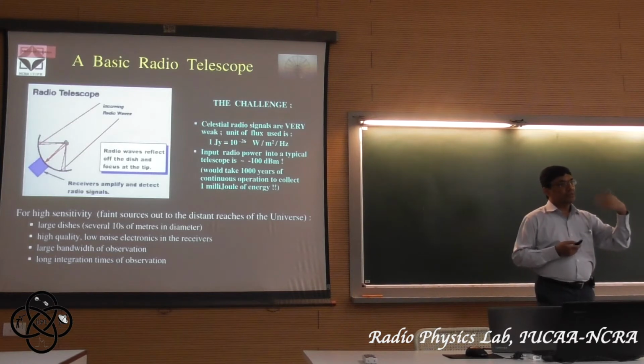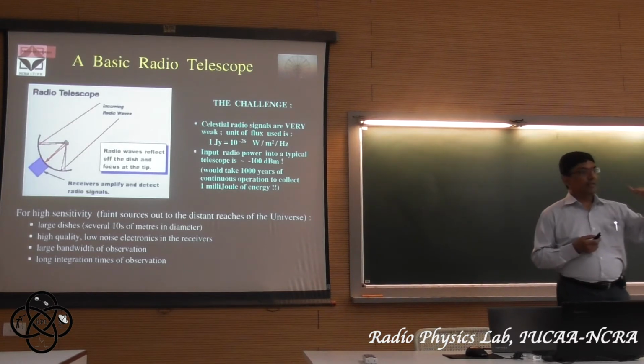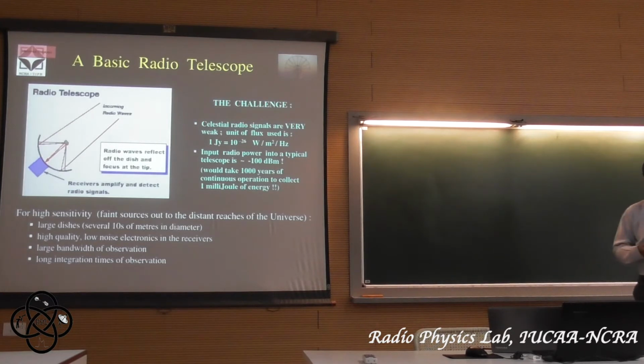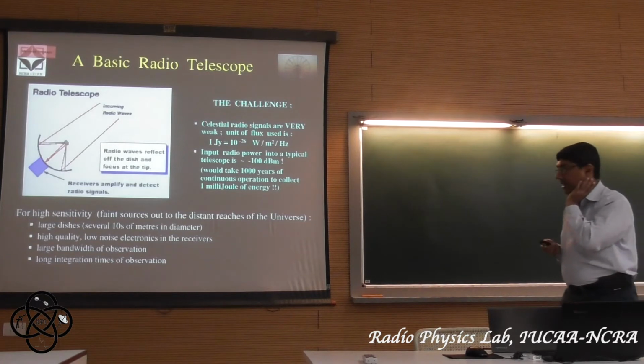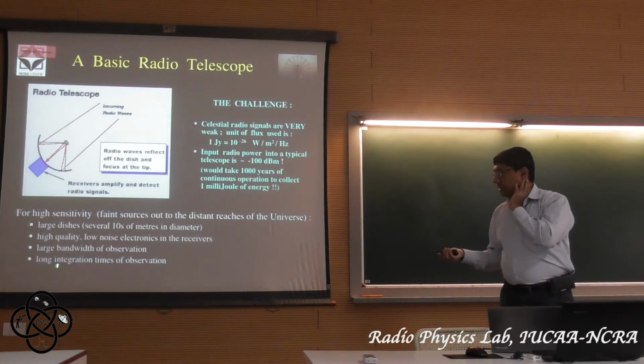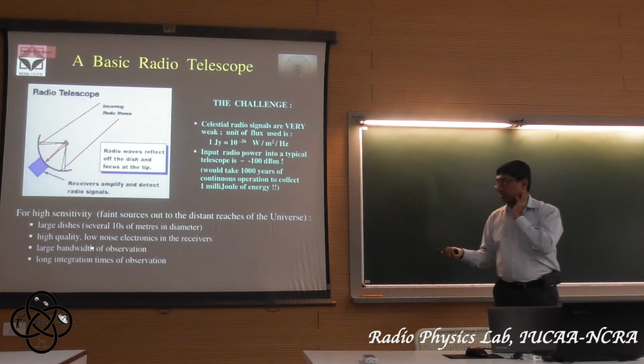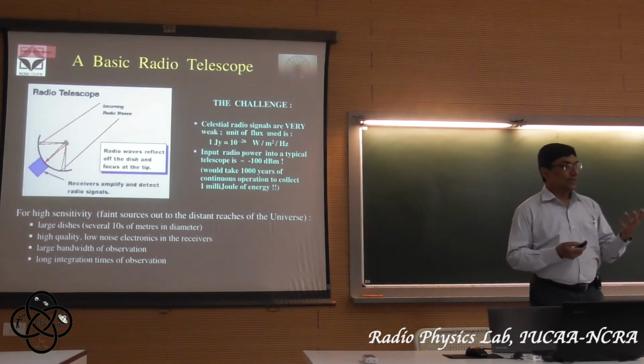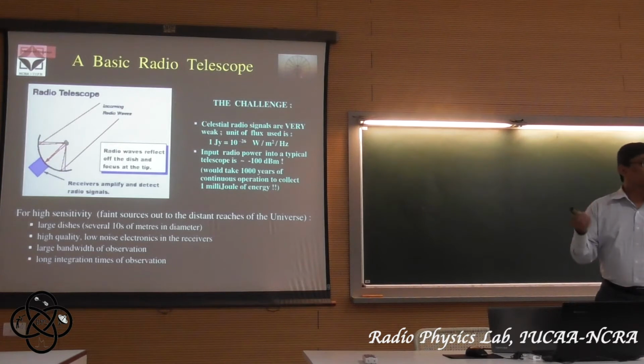So its strength does not grow in the same manner as the strength of the signal when you integrate. Again, I don't know whether you've come across these concepts in other talks or lectures, but basically the more bandwidth of observation you use and the longer you observe the source, the better signal to noise you can get with the same antenna and the same detector.